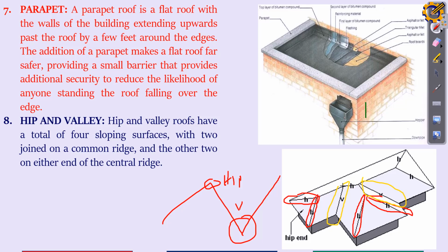Okay, so now the valley, there is usually a drainer inserted at the underside of this valley that actually allows water to come out. If you haven't noticed this, go and take note, if you have this kind of roof design. While at this hip, what they put there is a ridge cap, that flat metal. They just use it to conceal the space so that rainwater won't penetrate also. So on a hip, they apply a ridge cap. On the valley, they apply what? A drainer. So take note of that.